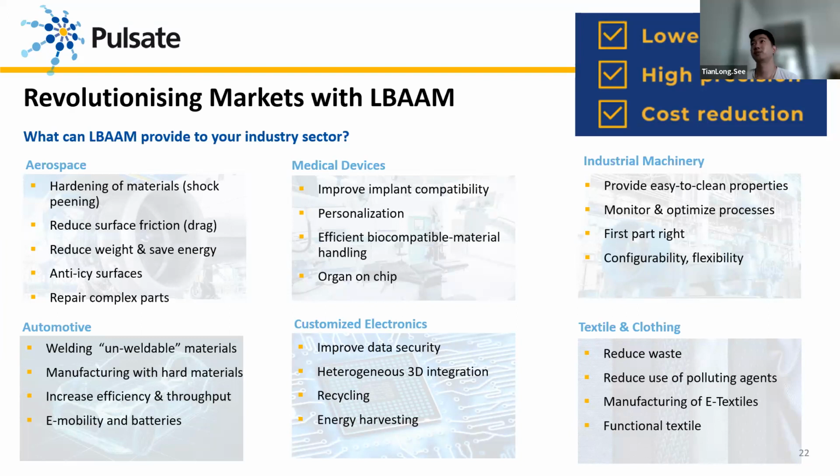Or it could be the case where you are in a very crowded marketplace at the moment with your particular products or components, and you want a market differentiator, and the thing stopping you is the limitation of the manufacturing processes. Then looking into laser-based manufacturing processes could be a potential way to expand the design or eliminate design constraints due to manufacturing processes.